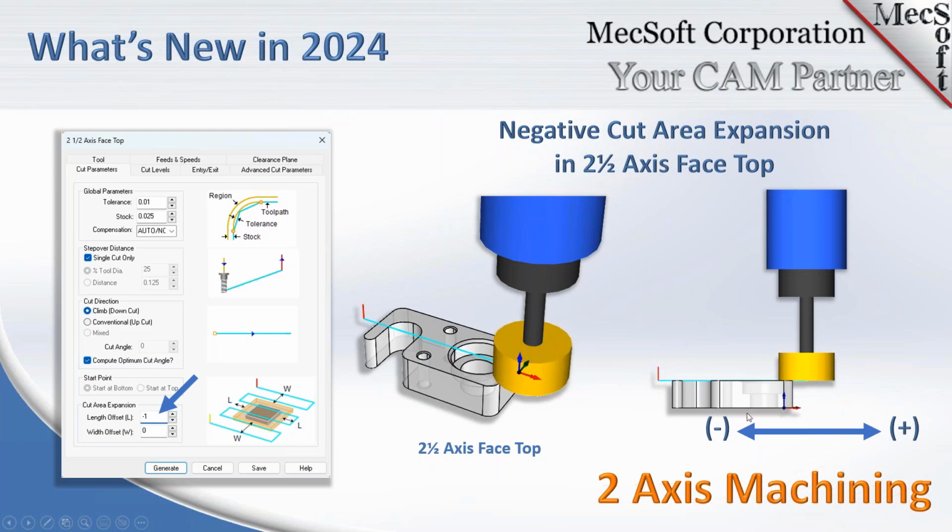Previously, the tool would go all the way past the part and clear the edge of the part. If the tool is sufficiently large, or even regardless of what size the tool is, you can now bring that tool in closer to the part by entering a negative value in the cut area extension.